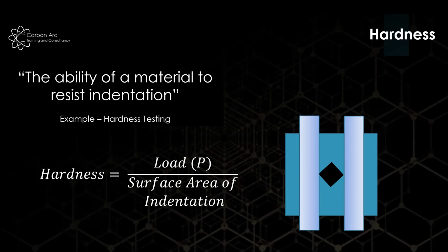Hardness is a good thing to understand because it links very nicely with brittle failure. If we have a risk of brittle failure, it's normally in higher hardness materials. So we can understand our mechanical properties and the risk of failure coming out the back of those mechanical properties.